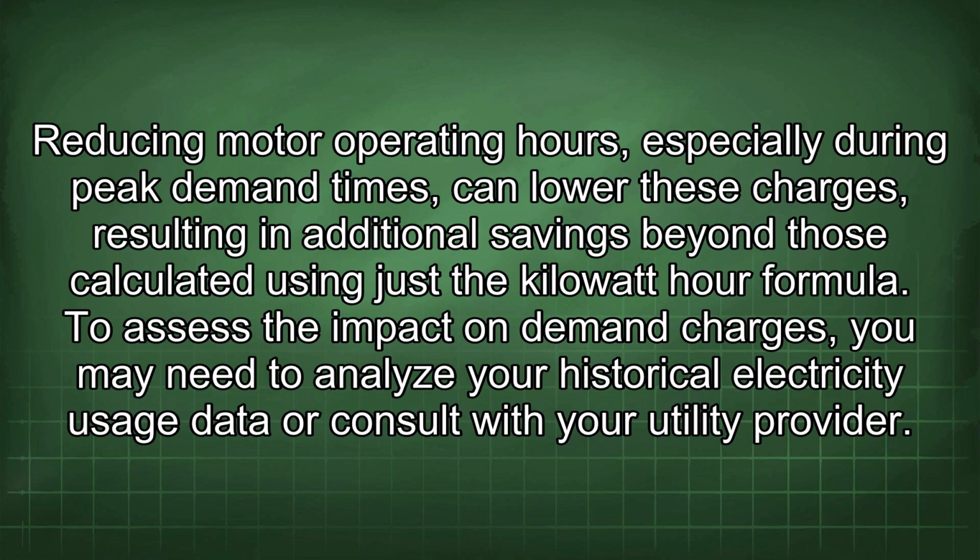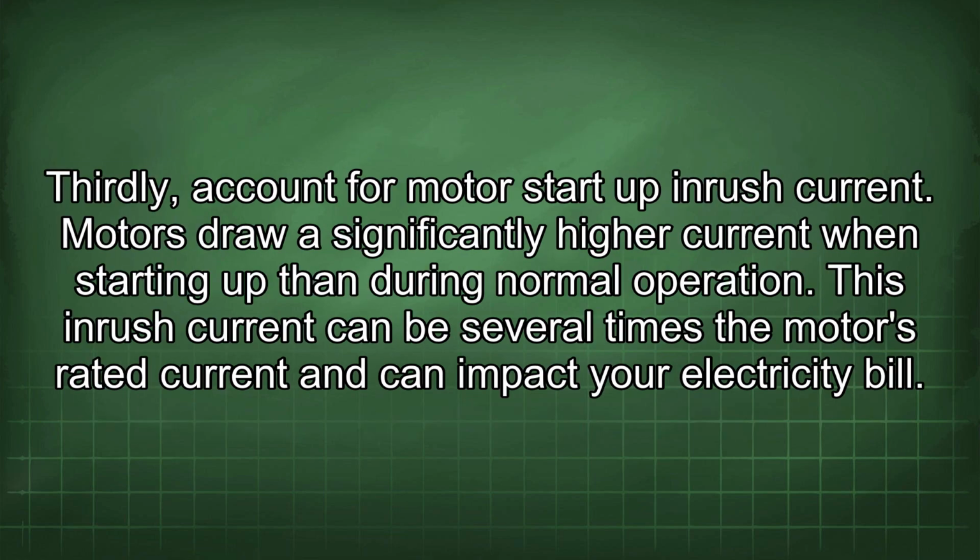To assess the impact on demand charges, you may need to analyze your historical electricity usage data or consult with your utility provider. Thirdly, account for motor startup inrush current. Motors draw significantly higher current when starting up than during normal operation. This inrush current can be several times the motor's rated current and can impact your electricity bill.